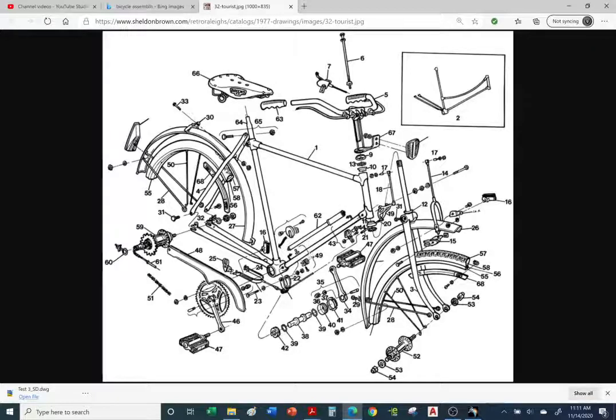They have their own individual detailed drawings of how each tube is made, how each rim or spoke is made, etc. How the seat is made, that's a whole separate detailed drawing with instructions of materials and how it's formed or machined. This is an assembly drawing. It doesn't show any manufacturing, sheet metal, or machining. It's just instructions of how to fit all the pieces together to make your machine, or in this case, bicycle.